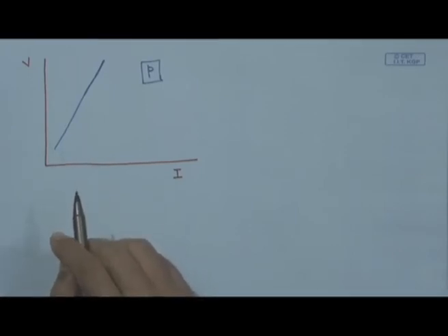Now, for all sputtering operations one may expect to have a certain cathode current, that means a certain cathode current density, power density, with a certain pressure and a reasonably applied voltage which is not too high. So, for this a special consideration has to be made in the design of the cathode.